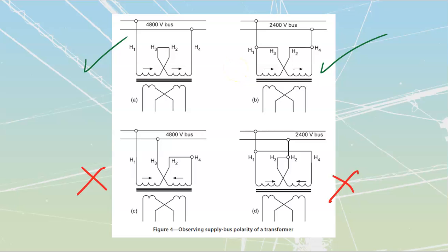What's the big difference between them? Well, if I take a look at this, this is my series 1. I see that I'm going in from 1 to 2 to 3 to 4. If I wanted, I could freeze time. We're going to freeze my line 1, line 2, with line 1 positive, line 2 negative. If I place a positive in, that would mean this would have to be positive, which would mean this would have to be negative, which would mean the other end of the H4 would have to be its positive, and the other end of the H1 would have to be its negative.